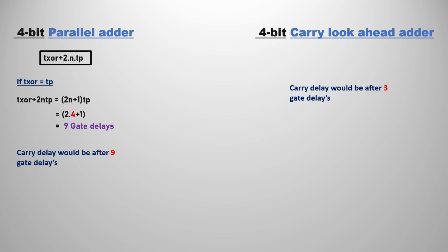We have already seen the logic diagram and the circuit diagram for the 4-bit CLA. From scratch up to the main thing, we have already described the circuit diagram for the 4-bit CLA. If you observe, that is 3 gate delays. You can see 3 gate delays is a very small time delay, so we can consider it the best 4-bit CLA.